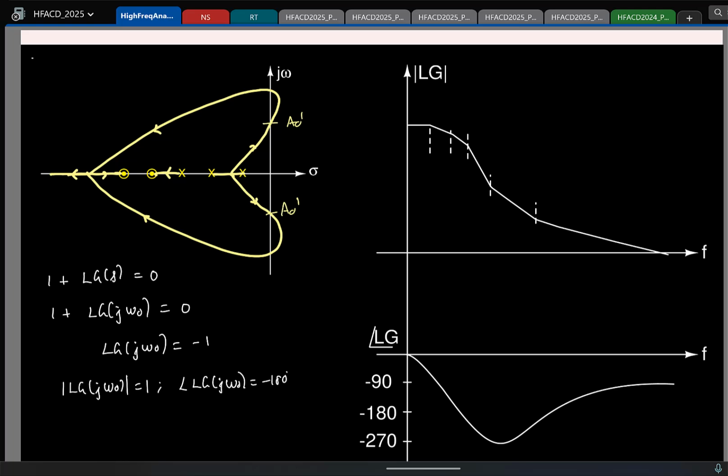And what is special about this DC gain A0 prime? Why am I looking at this? After this DC gain, the poles enter the RHP, right? So this is the kind of limit for you. Let's sketch the corresponding Bode plot here for this DC gain A0 prime. Let's say this is some A0 hat. The DC gain is some A0 hat here.